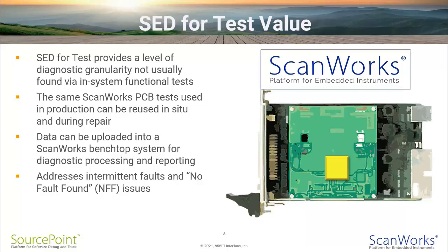But if SED for test is running on that PCB, if there's a fault, that data is automatically captured. So even if the PCB displays no fault found when it's returned to the depot, you have the information on the fault that was captured while the PCB was out in the field. So again, a very powerful application and use of SED for test.